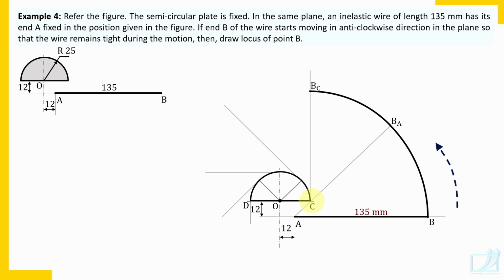We divide pi d in 8 parts. Here we are going to divide pi d by 2 in 4 parts. So this is initial position for the involute of that semicircle. So we'll proceed on this line. We'll measure pi d by 2. Pi d by 2, 79 millimeters. Calculate, use calculator. Calculate pi d by 2. That is pi r, 79 millimeter.